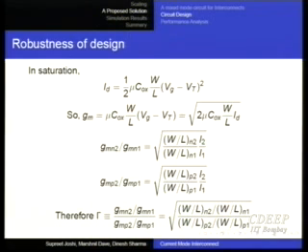You got it? When you took the ratio of N's, then the technological parameter cancelled out, and when you took the ratio of ratios, then the operating point cancelled out. Okay? So as a result, this gamma is very, very robust. It is dependent only on geometry. Okay? So it's also in that geometry, it is a ratio of ratios.